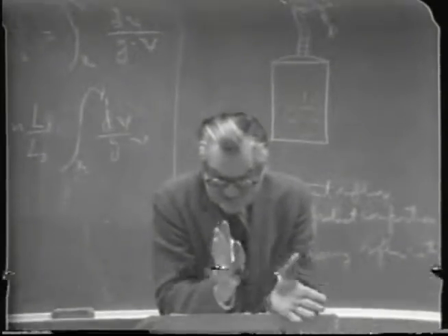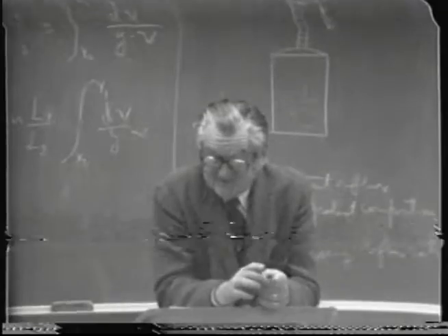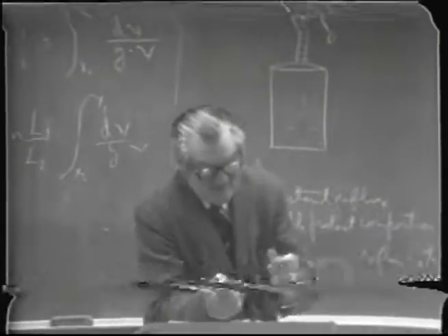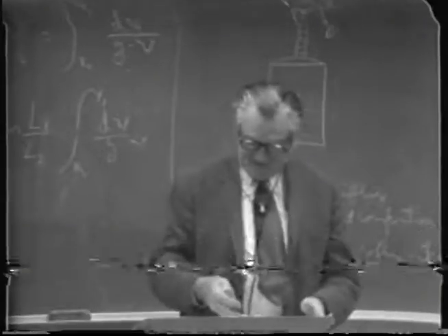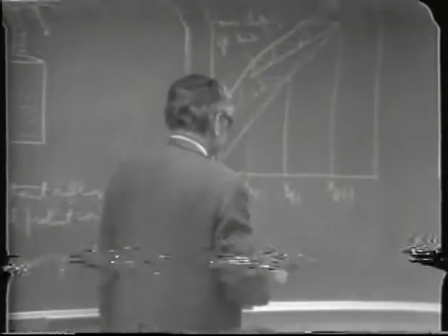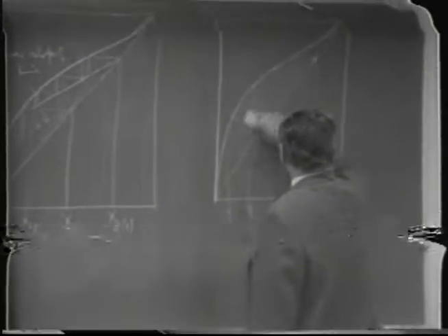It's sort of a comparable concept to the minimum reflux ratio we had before. You'd approach this value as a limit by taking the steps between the curve and the diagonal.